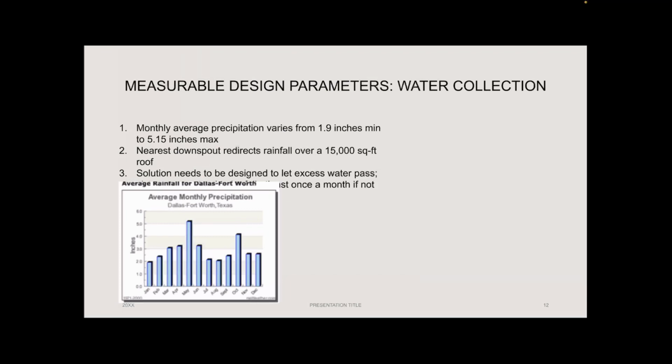If there's rainfall during certain months, we also have to account for the rain that falls on the 2,000 square foot piece of land we have, and that is more than enough to water the plants itself. So we could save the water when it's raining and use it at a later date. Our system will be sustainable just using rainwater, but just in case we go a long time without rain, we need to have a city water backup according to Ms. Deinhammer's specification.